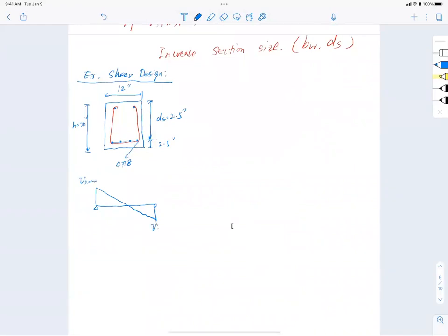But when you design it, you take a spacing of ds away from that, and this to the maximum point is the real Vu. Don't ask me why, I'll explain it in the next lecture, but this is max Vu.